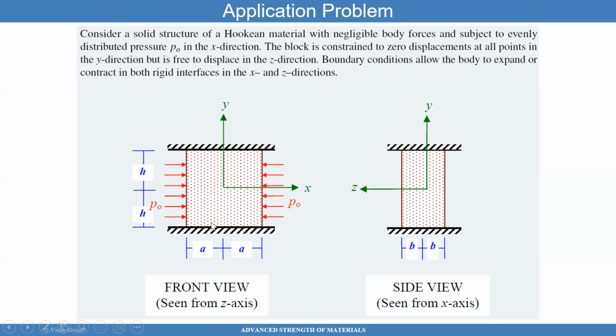or expand or contract. On these lateral surfaces, I'm going to apply a load of P naught so that I'm compressing that structure in that plane, in the x plane. So the surface perpendicular to the x plane. And on the side view, so that's the front view, I'm not going to apply anything, but I'll let it slide on the top and bottom surfaces. So the question becomes, what are the stresses and what are the deflections due to these loads applied? We're also going to assume that there are no body forces. So there's no gravity on this and we don't have to worry about it.